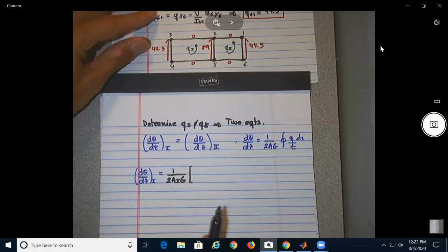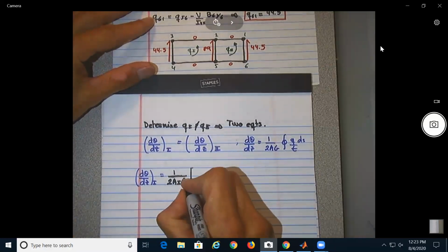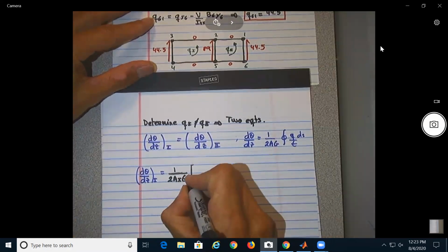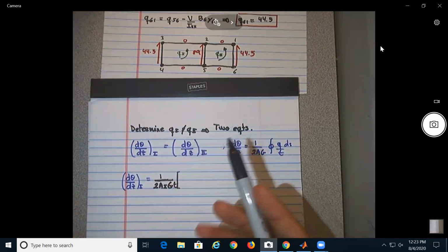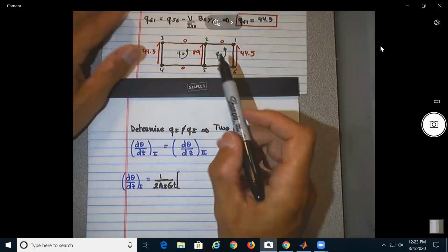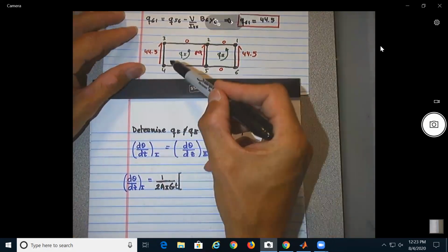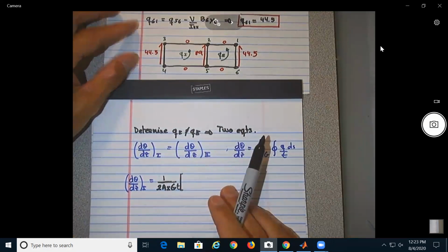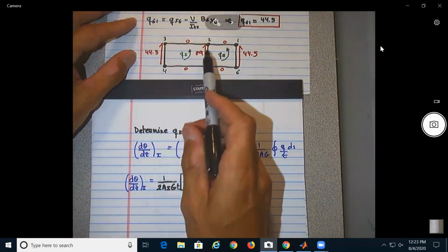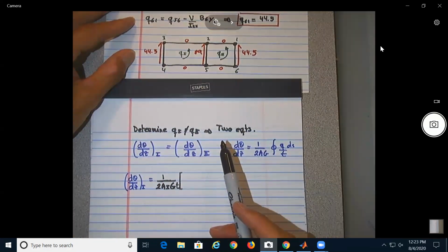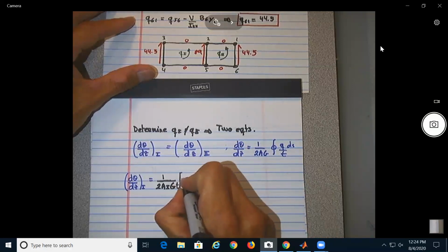Okay, and as somebody just mentioned in this problem, the t is constant, so we could put it outside over here. All right? So now, what I did actually to break it a little bit differently is that I said, okay, the Q1, let's say that is positive going counter, we're going to assume the angle of twist counterclockwise, okay? So Q1 here will always be producing a positive angle of twist. All right? So what I did on this one, I said there will be Q1. I just worry first about Q1